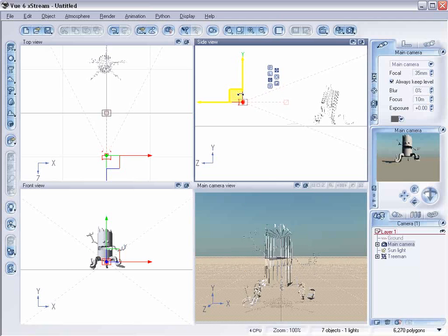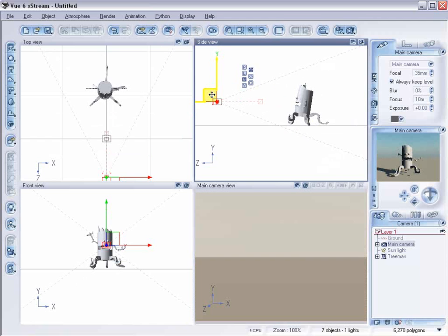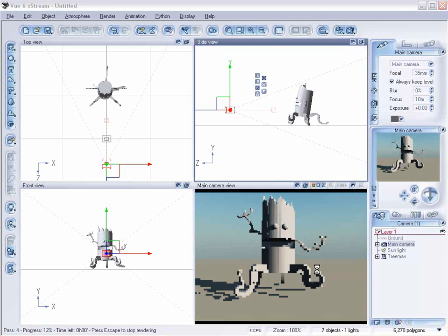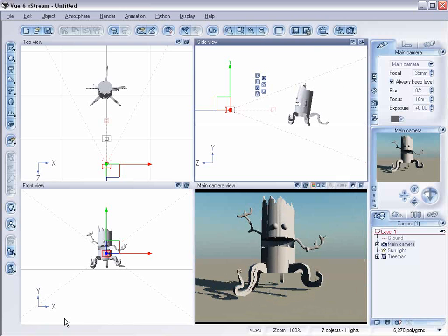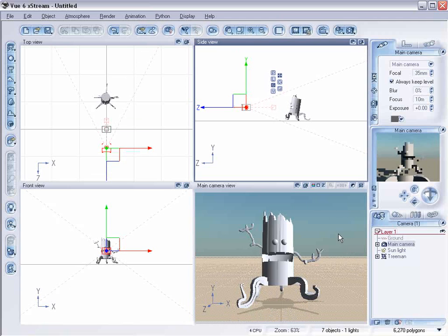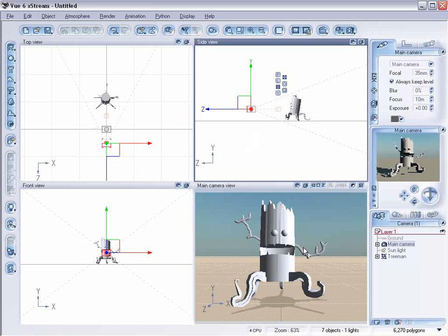And there's a couple things I want you to notice. First of all, the legs, they're not really on the ground. You need to kind of pay more attention as we're creating that in Hexagon and position them a little bit better. And then secondly, if you look a little bit closer, you see we have polygons here, and on some objects you might want to smooth those. But with this particular model, we may get some benefit from the lines when we add the bark material.